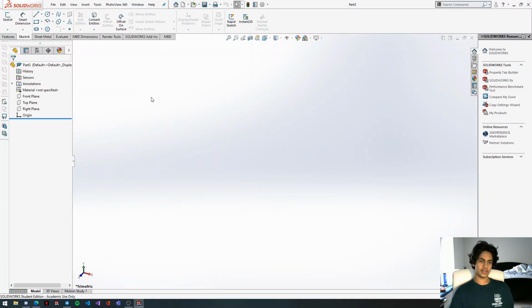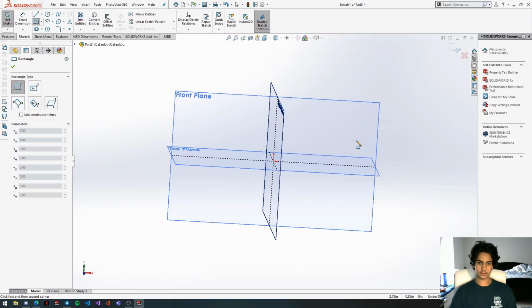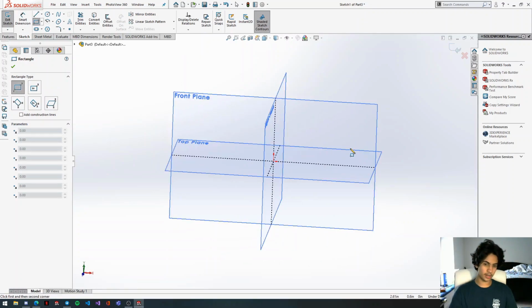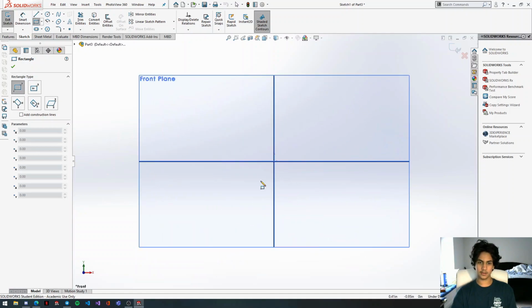We're going to create the drive plate, which I talked about before, the parallel plate drivetrain. We're going to create the one that goes on the outside. I didn't cover this in the first tutorial, but if you want to set specific alignments, you can hold down Control and hit space. And as you can see, we have this thing that pops up. So if we want it to be completely parallel to the front plane, we can select this face and there.